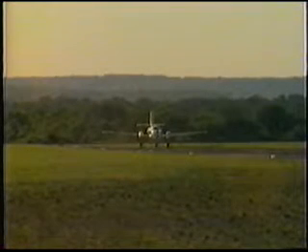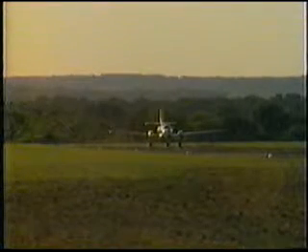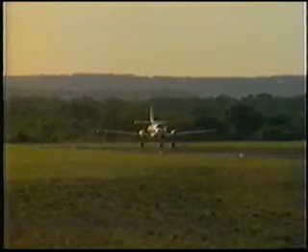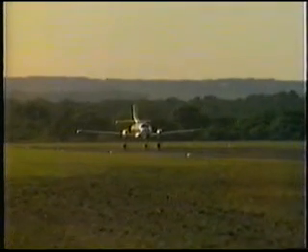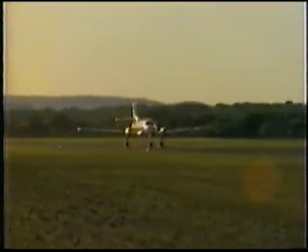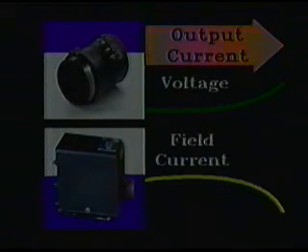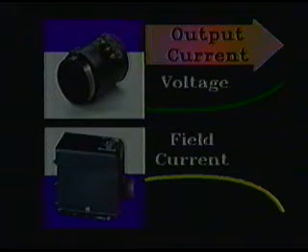Now the pilot has completed his pre-flight activities and begins to taxi for takeoff. As he advances the speed levers, the engine RPM increases. Since the generators are now being rotated faster, they would produce more electrical power. Again, the generator control panel senses this condition and decreases the strength of the generator field to maintain the proper output voltage and load sharing.